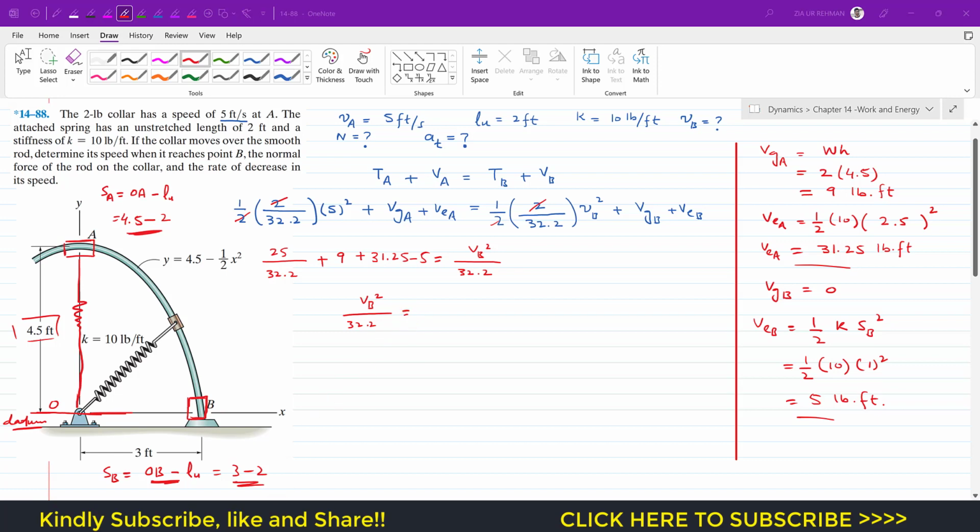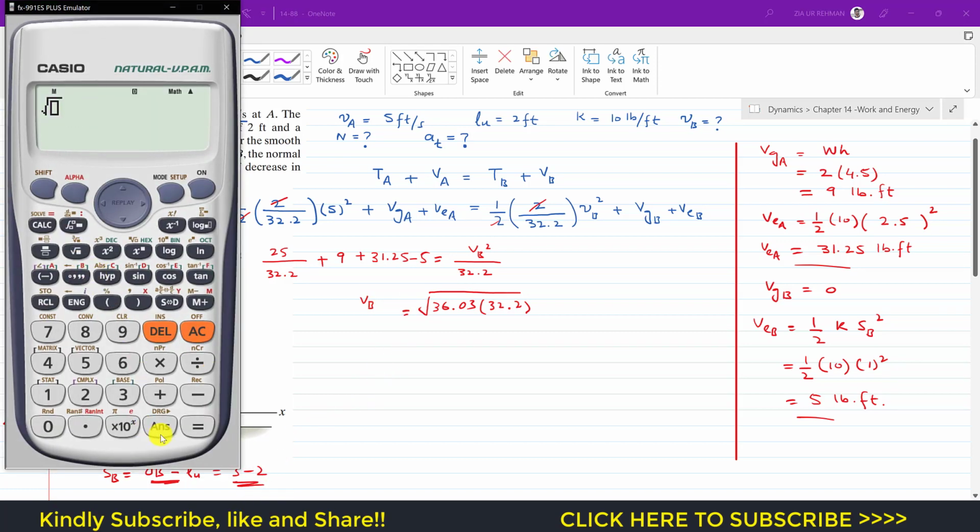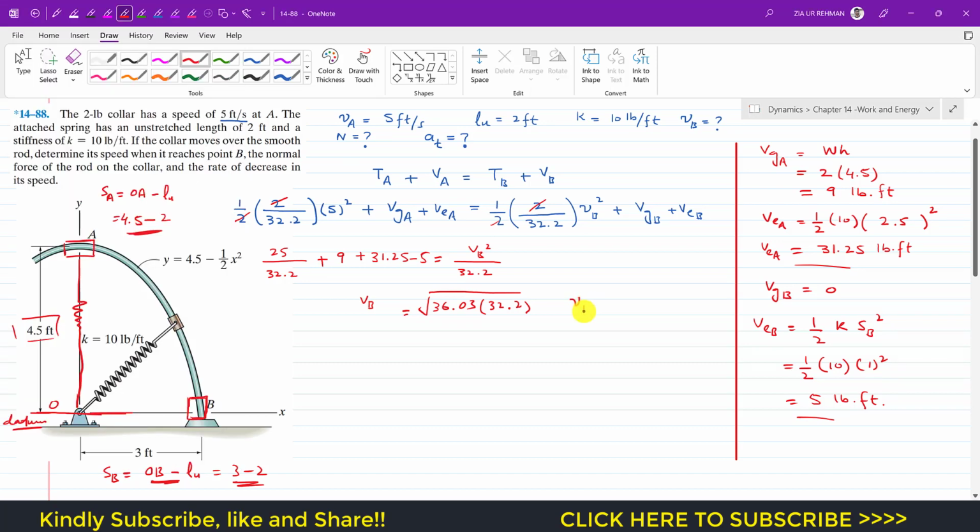So we can say that VB squared divided by 32.2 is equal to 36.03, and we can say that VB squared is 36.03 times 32.2, and if we take the square root, that will give us the velocity of the collar when it is at point B. So 36.03 multiplied by 32.2, and the square root gives us the velocity equal to 34.06. So VB is 34.06 feet per second.